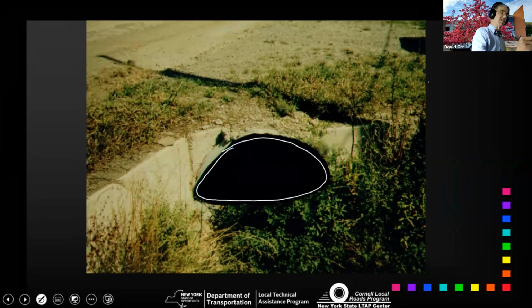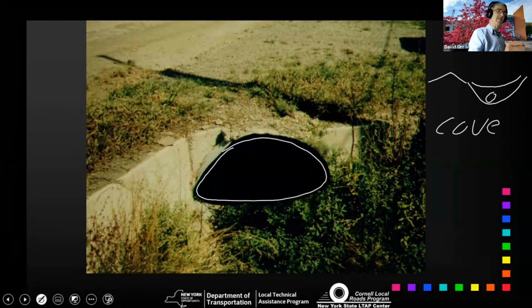When it comes to deciding what the shape is, a lot of times we're dealing with ditches. And if you're dealing with a ditch, you've got a ditch like that. You want to put a driveway with a swale in it so that the water doesn't flow in the road. And I'm going to put my pipe inside that ditch line. Do I have enough cover over the top of the pipe so I don't break it down? I'll show you that before we're done here. The minimum cover that you need in every single case, by the way, is 1 foot if it's properly put in. Okay, so do I have that?